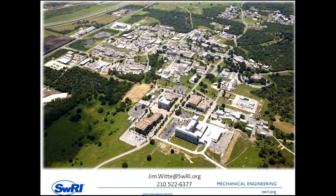But also at certain minimums, like 1 to 2 feet per second, you don't produce a stable velocity profile. It's always turbulently changing, and so that in my mind would be a place that you would want to avoid in terms of trying to produce high quality flow measurement.